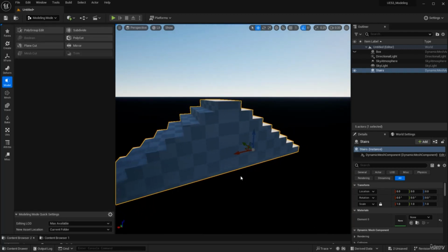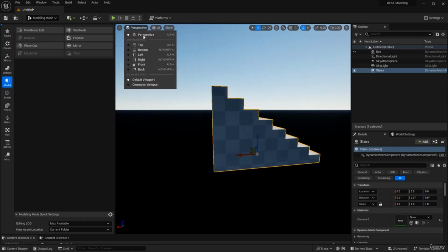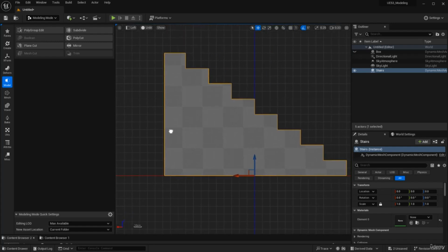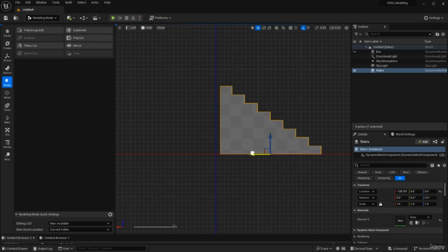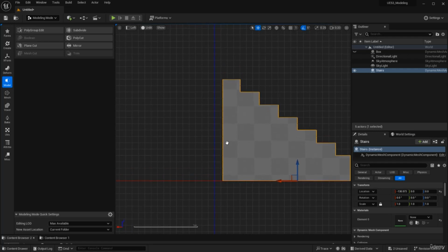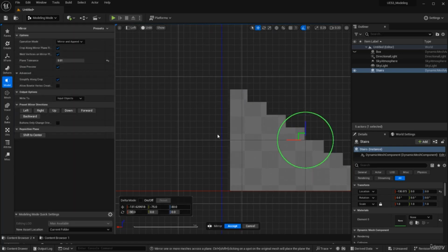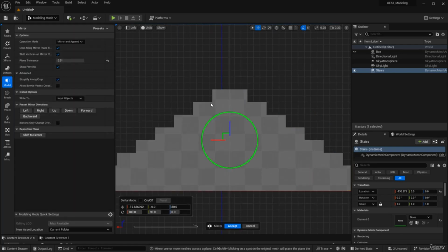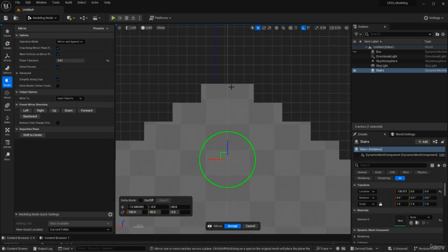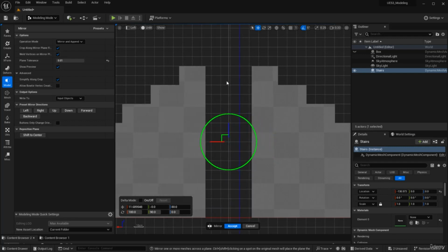And another thing, let's go ahead and undo that. So if I go ahead to the left again and move this stair there, so let's say you want to mirror the 3D model on Z axis, and if I go to a mirror and click forward, you can see it's mirroring based on the closest point on the object. So you can move the plane, you can click and move the plane. You can see this white line, this is the plane.